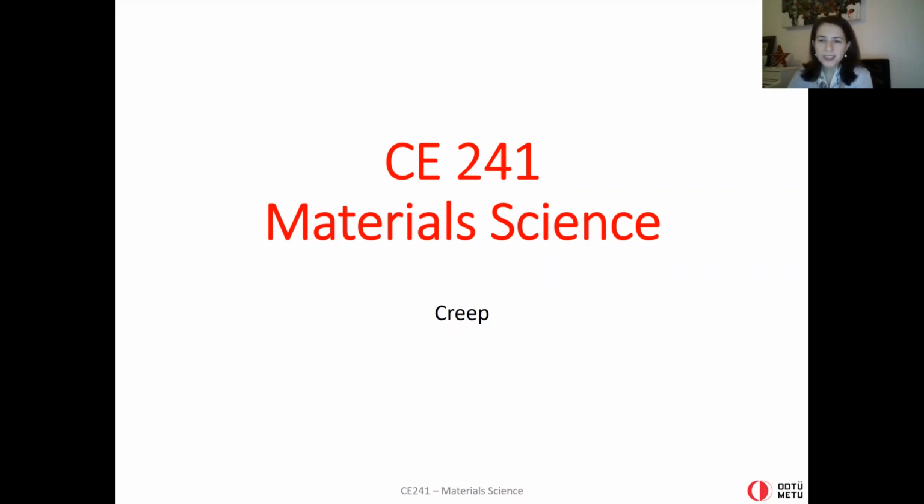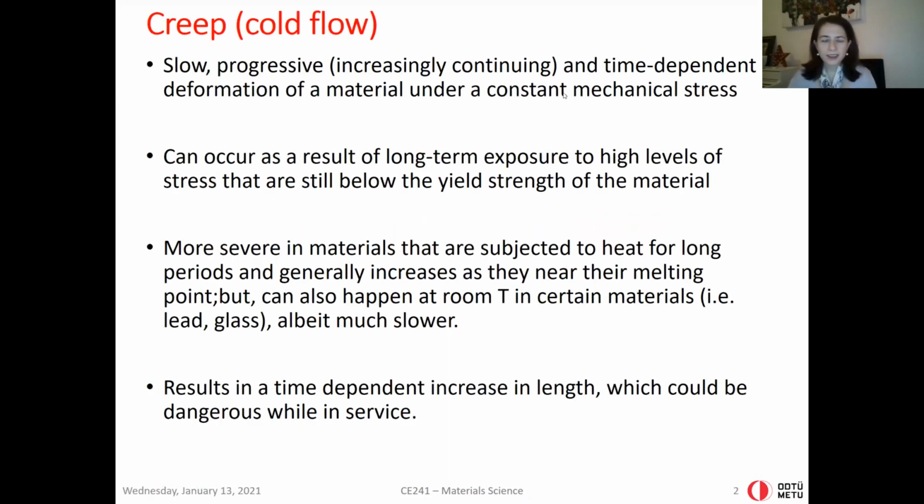241 Material Science. Today we're going to discuss creep. Creep is also known as cold flow. It is slow, progressive. Progressive means increasingly continuing and time-dependent deformation of a material under a constant mechanical stress.